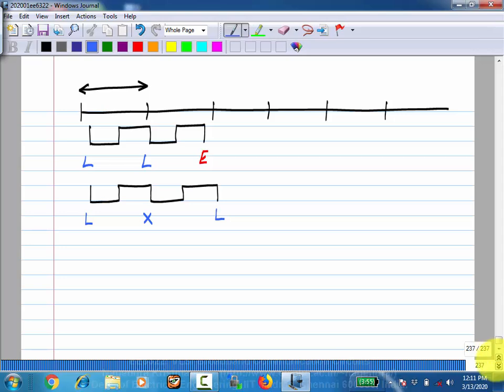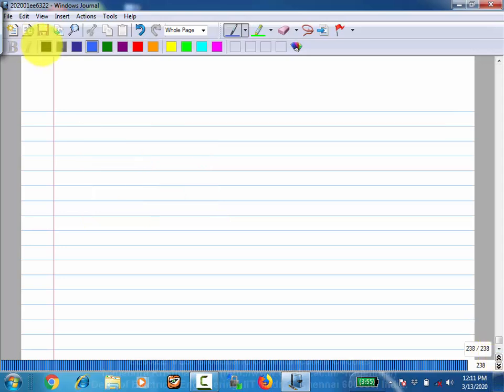Now, next we will go to a slight modification of the bang phase detector. Essentially what happens is that as you go to higher speeds, you have to generate this high speed clock. That clock is what is driving all the data, the decision latches and all the other latches or flip flops you use in the phase detector.